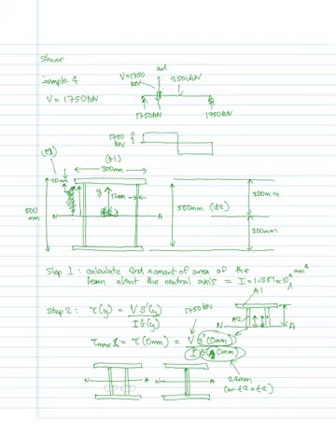The important bit here is that since we're talking about stresses, when we substitute b at 0 millimeters at the neutral axis, we do need to include both breadths, or both thicknesses, of the web.